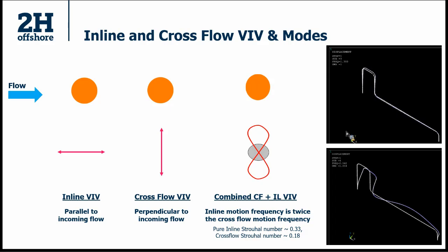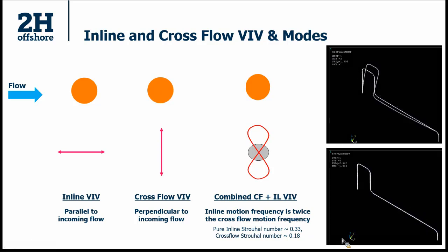Basically, the pipe is pivoting around the two connectors where it's connected. If you imagine standing with your legs a bit stretched out, and you move back and forth a bit, that's how your out of plane vibration is. The second animation here shows your in-plane vibration mode. Again, in our analogy, if you're standing with your legs stretched out and you move from side to side, you can imagine that's the mode of vibration for your in-plane direction.